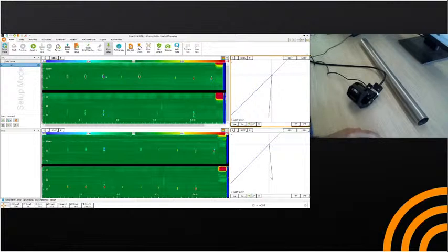So at this level, this is the second pass I did. Here we have the 6 axial cracks, and here you have the 45-degree. And the transverse notch will appear in the transverse C-scan. And you can see how we were able to detect these defects.